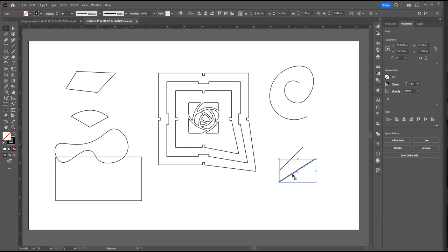And then now with the Control D tool, it's the duplicate keyboard shortcut. I really like keyboard shortcuts, so that's what I'll use first usually, unless it's one that I just don't remember. Then with dupe, you can actually start making lines on the same angle. You're basically doing the same movement over and over again that you did before.